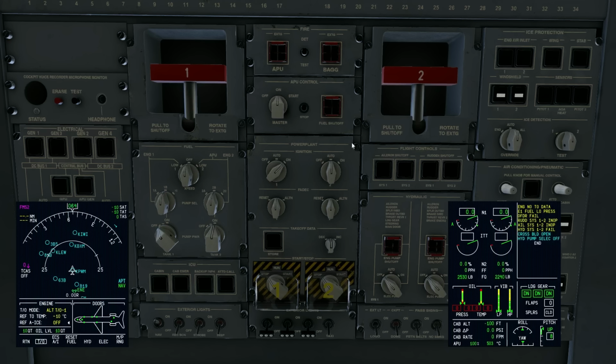So whenever it's below 10 degrees and there's water on the surface, or you're in icing conditions, or it's raining, we also run engine anti-ice on. We may not do the wings, but we will do engine. So for that case, for example, right here in Portland, it is snowing. There is snow on the ground. Because we have snow on the ground and we're below 10 degrees, we're actually at minus 10, we'll go ahead and say, yeah, we're going to have engine anti-ice on.